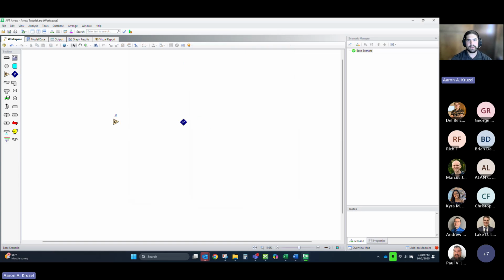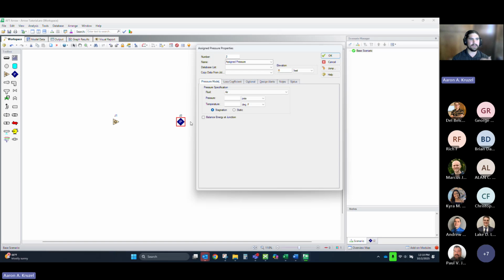From there, we want to have an end pressure. So let's say the end user, a control valve, an air drop, anything that would use a pneumatic system and control system for air, it's going to require a certain amount of pressure. So let's say our pressure that we're desiring is in PSIG, and we're looking for 100 PSIG. And let's just assume there's no temperature drop, 70 F for our outlet.